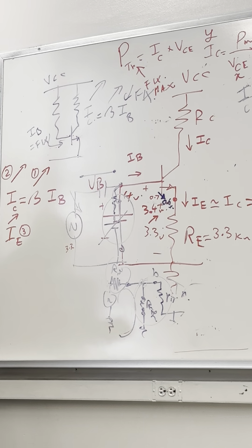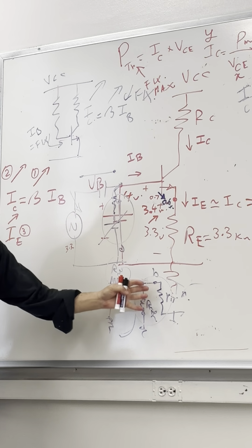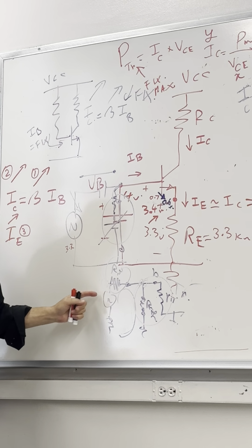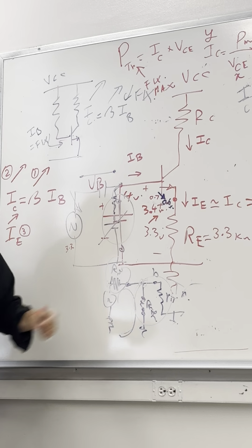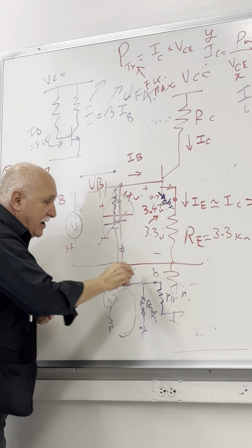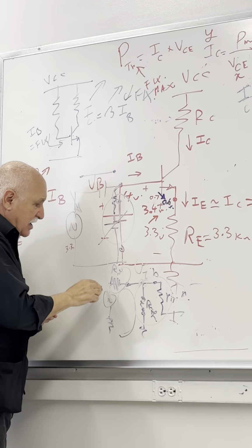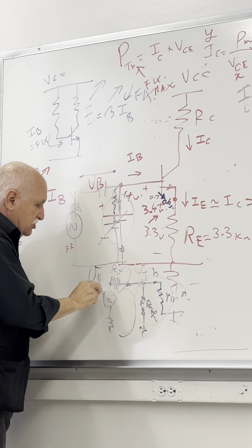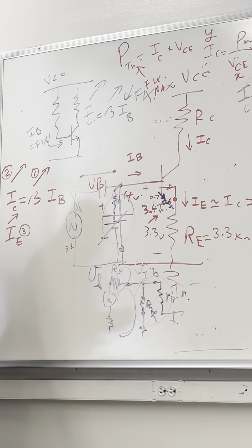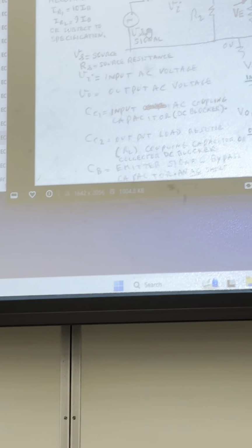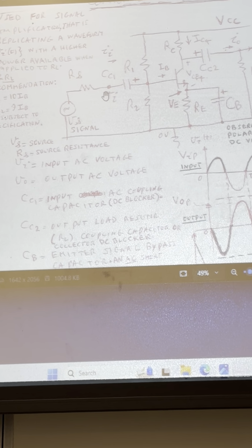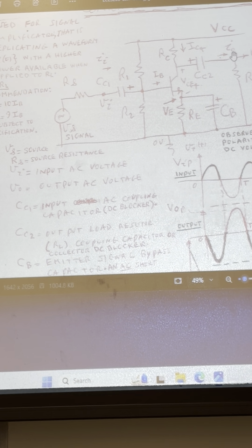And that is the reason why we want a relatively higher input impedance, so we don't lose much of the signal over here. So this is the VI actually, and that is the VS, the signal. Here, V signal, that's the V input. A captured portion of the VS. And then it's that signal that we will amplify, get it enhanced at the output.